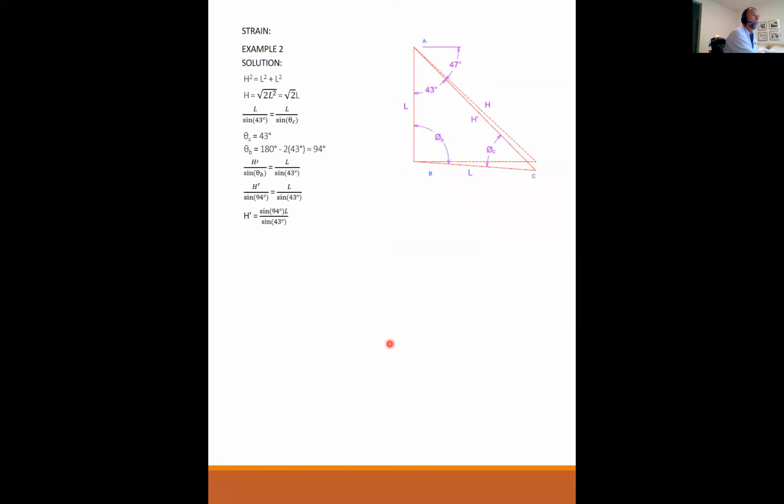Okay, so we went all the way down here, and now we get to shear strain. If we start with a solid block of some material, this is indicating a fixed surface, and this block cannot deform along this edge of the fixed surface. So think of this as a block of rubber that's been glued to the floor. You can push on this block of rubber and it's going to deform, but not at the floor where it's been glued.